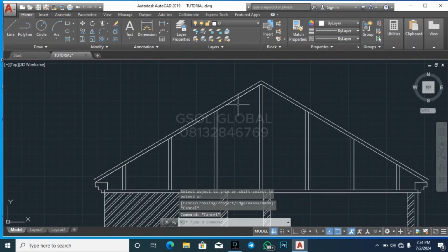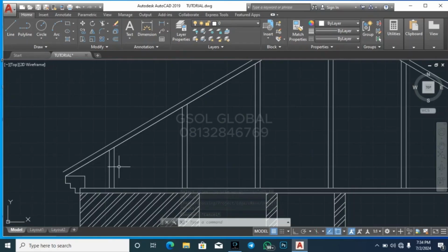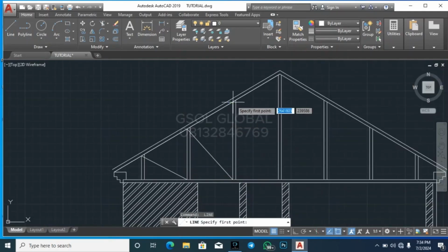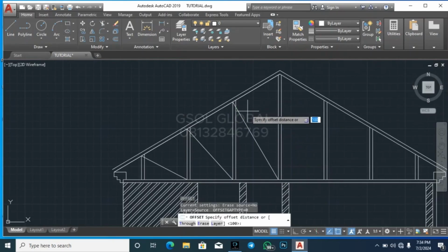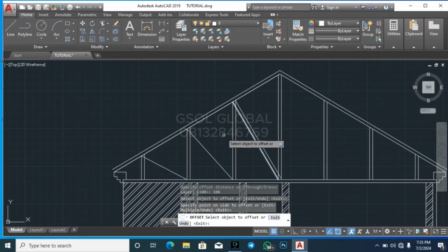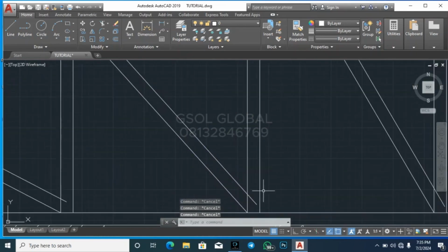so now what we are going to be doing next is to be drawing our strut, joining each king post for the strength sake of the roof. All right, so I'm just going to do this right away. Good, yeah. And then just draw one line each. All right, don't worry, you'll understand why I'm doing this. So we're going to make an offset of, let's say, 100. Okay, 100, right? Instead to this point and to this point. You see it, right? So that's how you go about it.